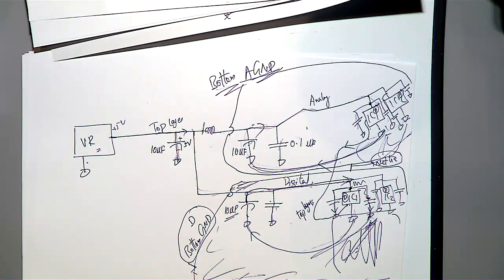You got digital ground because you got digital ICs. Then you got a USB ground, then you also got one more called a power supply ground. So you got 4 grounds in your DSO. And then in the DSO, again as we made it a bit complex, because it's easy to put 2 grounds, but then we put 4 grounds. Even when you have 4 grounds, as I said, you can connect the net tie.